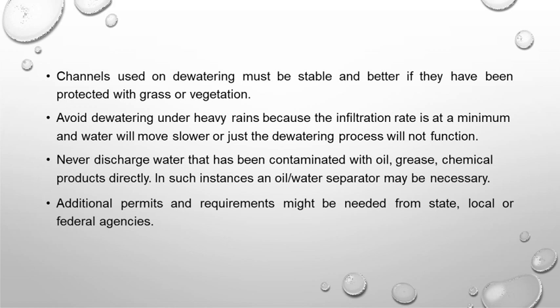The liquid attains a higher velocity and pressure at the outer periphery of the impeller. With the help of the special shape of the casing, that is a volute or vortex or diffuser, this high velocity energy is converted into pressure energy and the velocity is reduced. Now this water at higher pressure rises through the delivery valve to the desired height. So this is the working of the centrifugal pump and the reciprocating pump. These are mostly the two pumps used for dewatering purposes at construction sites.